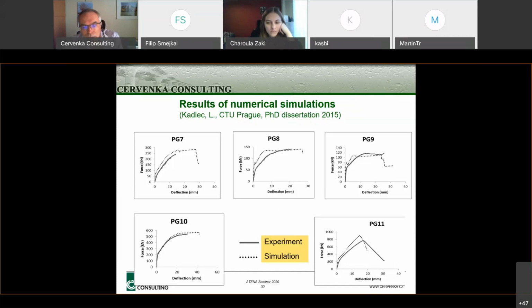So these parameters we have to use to always consistently generate all the materials necessary for our analysis, because typically we know only compressive strength, but in nonlinear finite element analysis, we need much more parameters. The ATENA model has about 10 material parameters. So in order for this study to be meaningful, we need to have a given rule for how to derive all the parameters from the compressive strength and use that rule throughout our study.